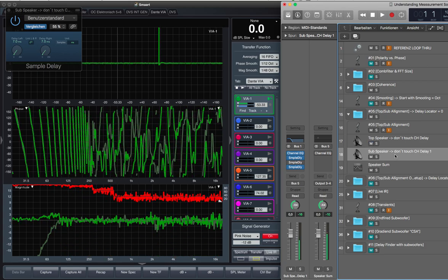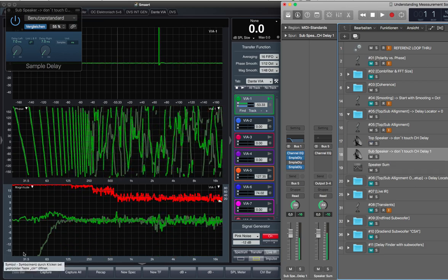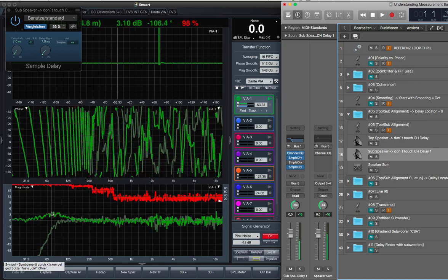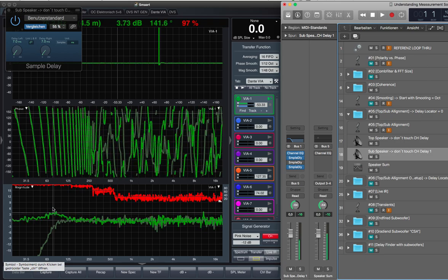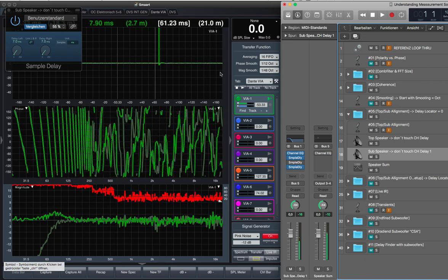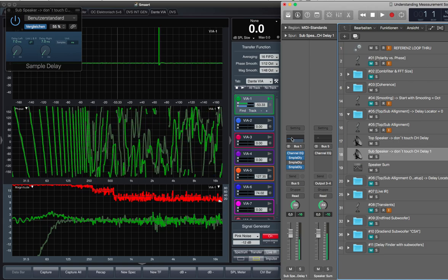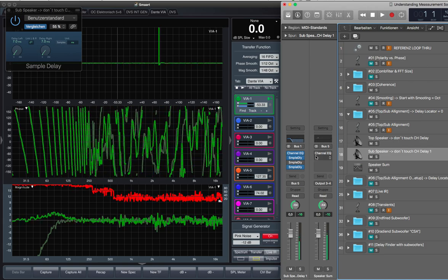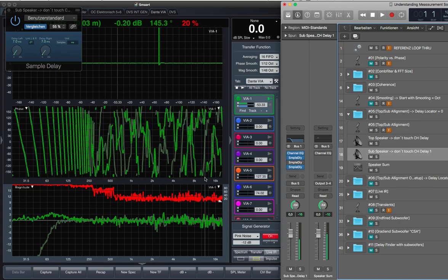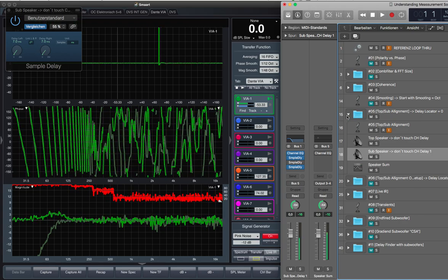And with both systems on, you see there is a 3 dB peak here. This is because I didn't use Linkwitz-Riley filters, which can avoid this, but Logic is not able to set the low pass and the high pass filter to Linkwitz-Riley. So yeah, we have to correct this with another EQ, but that's it.